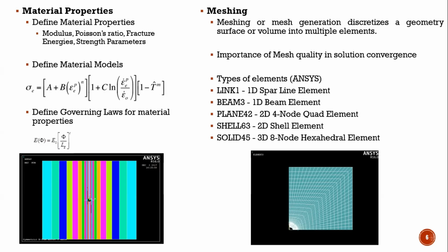For that, you need to write some code in a language such as Fortran. Once you write those codes, you can integrate your material model into the software package, or else you can just use some predefined material models inside the software package, such as this model. And for composites, we use Hashin damage.